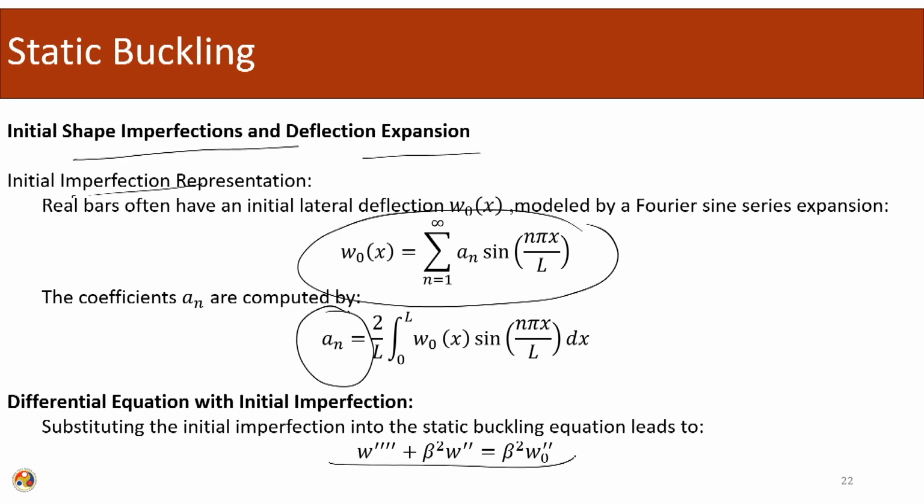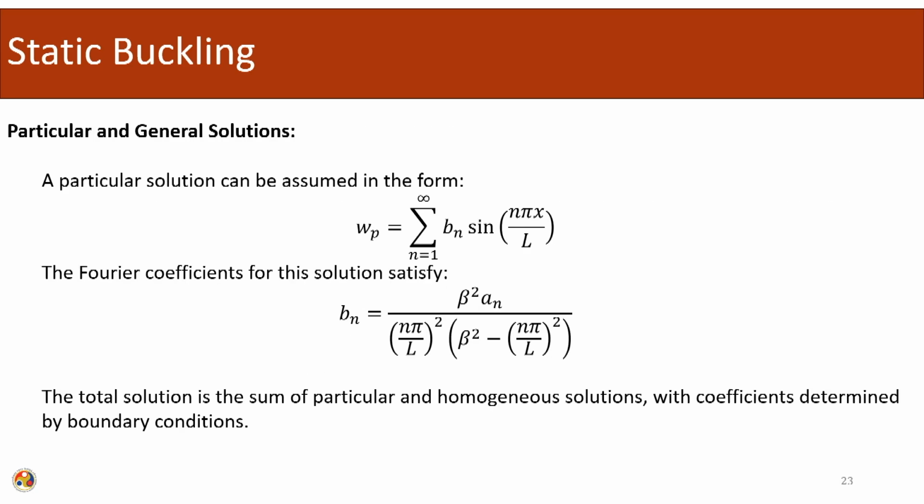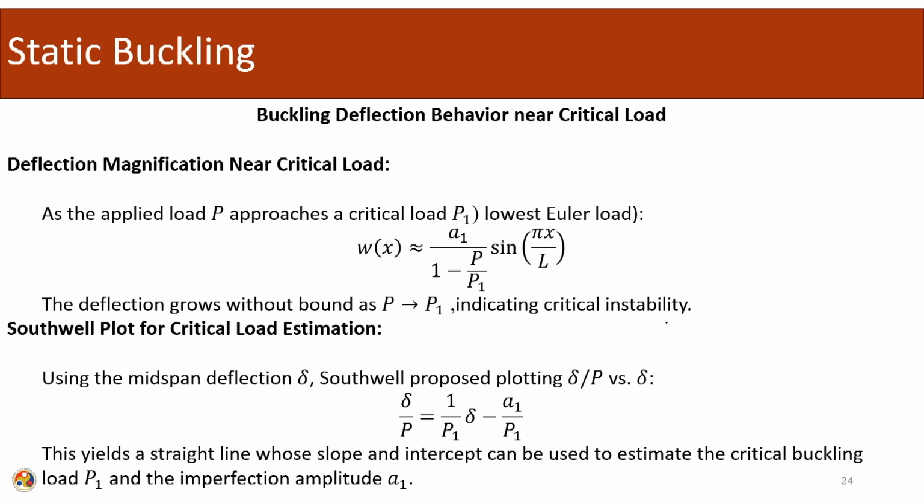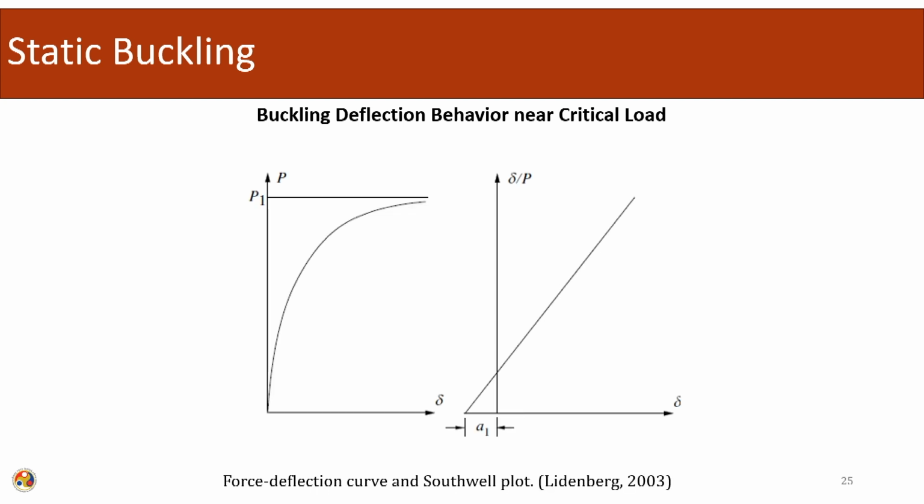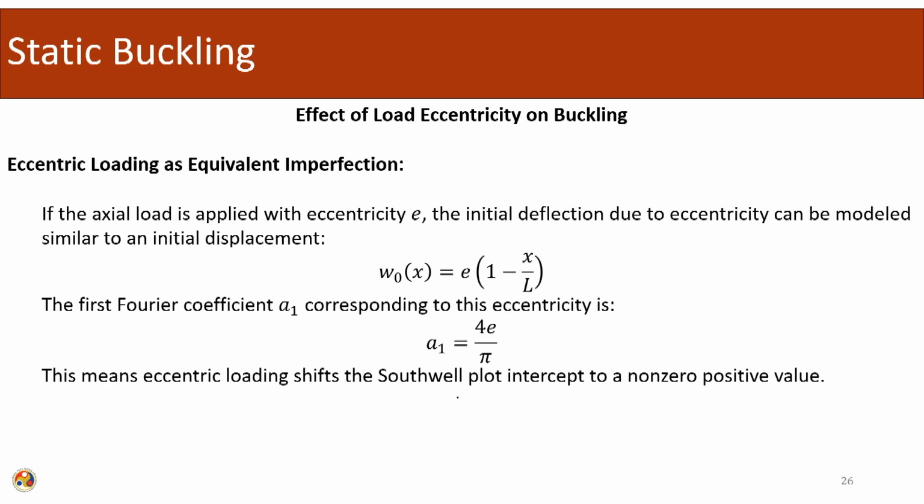And this is the differential equation. After that we put it into the differential equation, and after that we got the particular and the general solution. And then we evaluated the behavior of the buckling. So after that we did a Southwell plot. So this is being again asked in this particular question. And using the Southwell plot we can determine the coefficients.